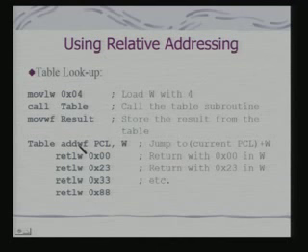This instruction ADDWF is a routine instruction in the sense that it can be used with any register, but here it is interesting because it is using PC, the program counter. Okay. So, current PCL, part of the program counter, is used as an operand. Now, this feature is not typically supported in many instruction sets. That is, you really cannot use PC as an operand in an instruction, but PIC provides the support for this kind of an instruction. So, what is it doing now?